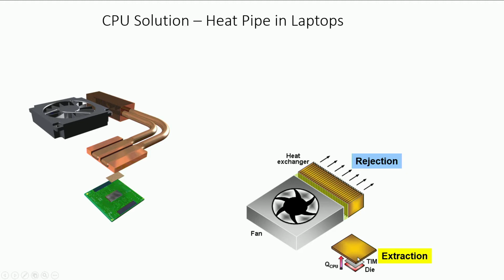So, why is it done here? Because this fan and heat sink is too big to be put inside on the motherboard in the laptop. Laptop, as you have seen, has a certain thickness, and you have the motherboard cutting through around half, maybe not exactly half. But again, the real estate, what we call the internal Z height of a laptop, the entire one is not going to be available on top of the CPU to put this heat sink.